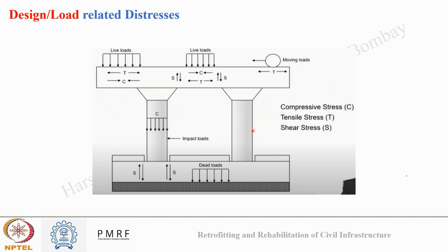Now, when we talk about a complete infrastructure, the structure is subjected to different types of loading. These loadings can be classified into three main types: dead load, which is due to the self weight of the structure; imposed load, which is constantly placed on the structure, like furniture or non-structural elements or devices; and live load, which is moving load, like humans or vehicles. Some other forms of load that are also considered in design include earthquake load and wind load. Through known standards and provisions, we take these actions into account also.